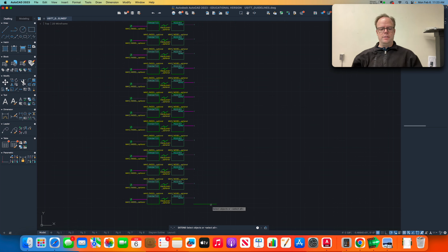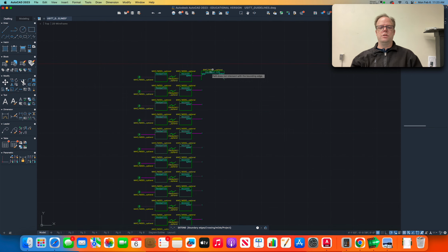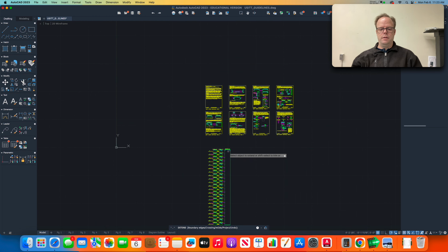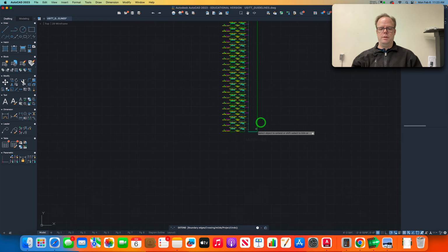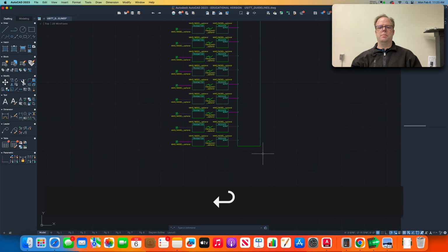And what you're doing is you're selecting the place that you want to extend the lines to. And that is this line I moved. So I'm going to click on that. Enter. Okay, and now it says select the objects to extend. So I'm going to go up here and click on that line, and click on that line, and look what it did. It bumped them all down to that bottom line. And then I can hit enter to get out of the command, or escape.